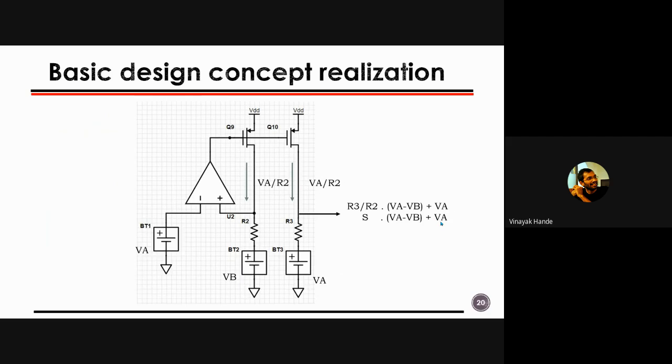But now somebody will argue that all these batteries you have connected, but if I have a battery, then what is the need of a reference voltage, right? At the end of the day, we were designing a voltage reference because we wanted some voltage which does not vary with the temperature inside the IC. If we are connecting all these batteries, then this circuit does not hold true at all.